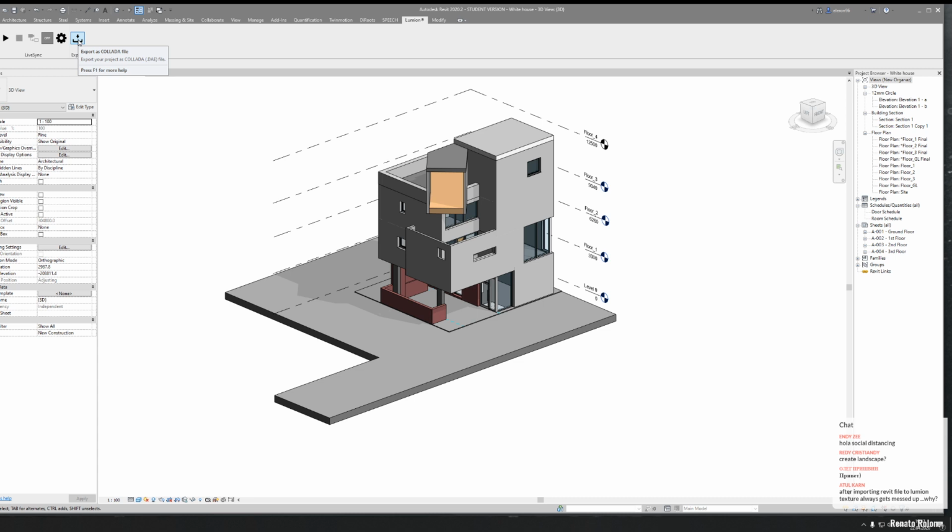So I will use only the second way. I will use the export. Let's export our file. You will get this point of view. Like surface smoothing, you need surface smoothing if you have a building like a Zaha Hadid building, but if not, don't use it on the high. You can leave it on something average between the normal and high. Just leave it as it is. The collect texture option is an important one, because we have different textures, as you remember, we did different materials, and this is so important for us.